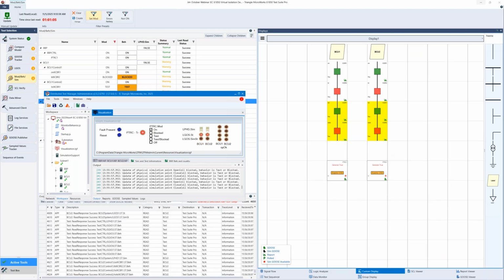So if a device is subscribed, let's say, to 3 GOOSE messages and 1 sample value message, and at a certain moment for one of the GOOSE messages, a simulated one is available, it will still continue to listen to the other ones where no simulated message is available. So it only switches the reception of that stream to the simulated one where there is one available.